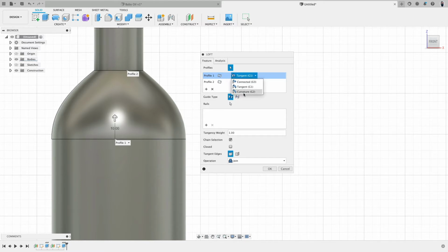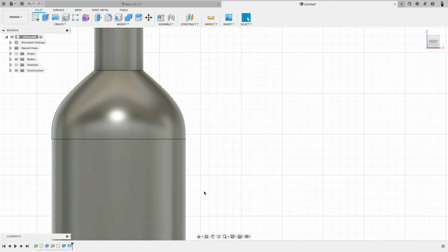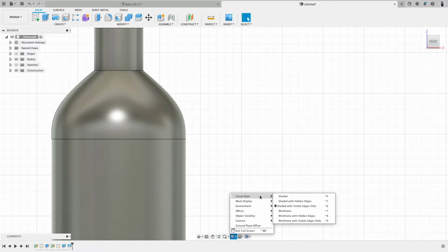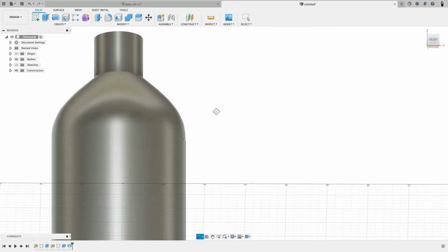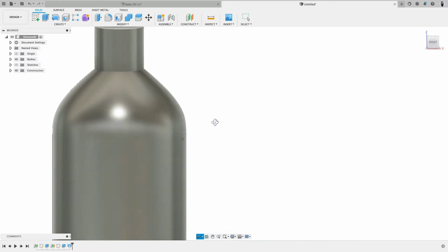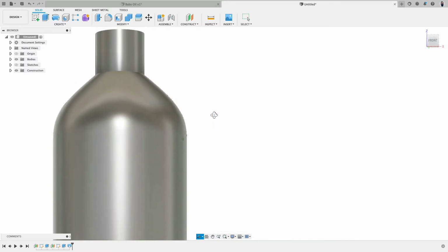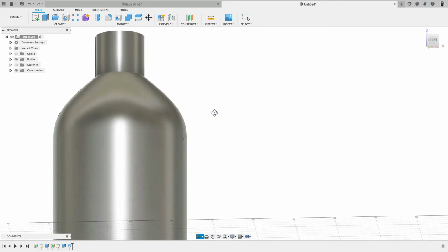transition. When we go to G2, you notice that this is a little bit longer, so the surface goes straight up and then continues and then slowly blends. So a much nicer flow. Let's take a look at this. We will go to here and go to shaded and then rotate our camera. Pay attention to that highlight. It's a small ball and now it gets into a line.